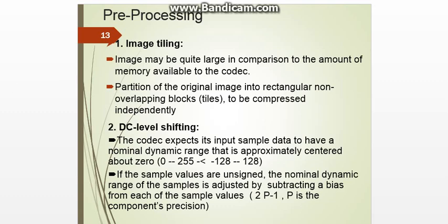Now we can decompose this whole compression engine into three parts, that is the pre-processing, the core processing and the bit stream formation. In the pre-processing part, the image tiling, the DC level shifting and the component transformations are included, and in the core processing part, which consists of the discrete transform, the quantization and the entropy coding processes, and finally the output code stream is formed.